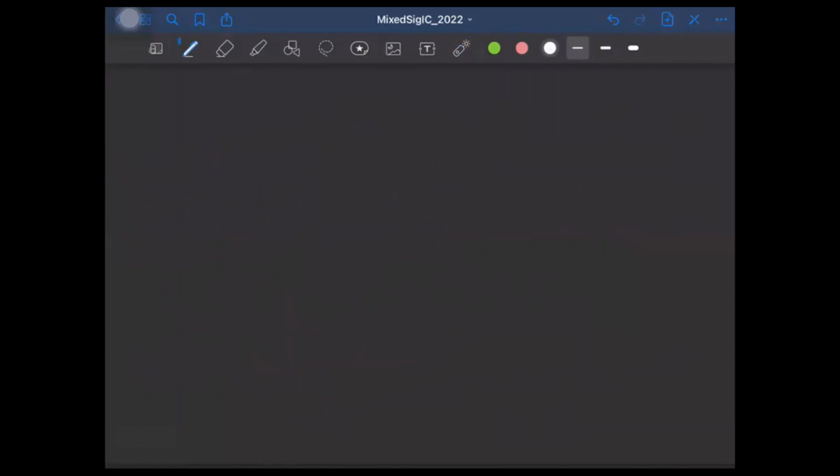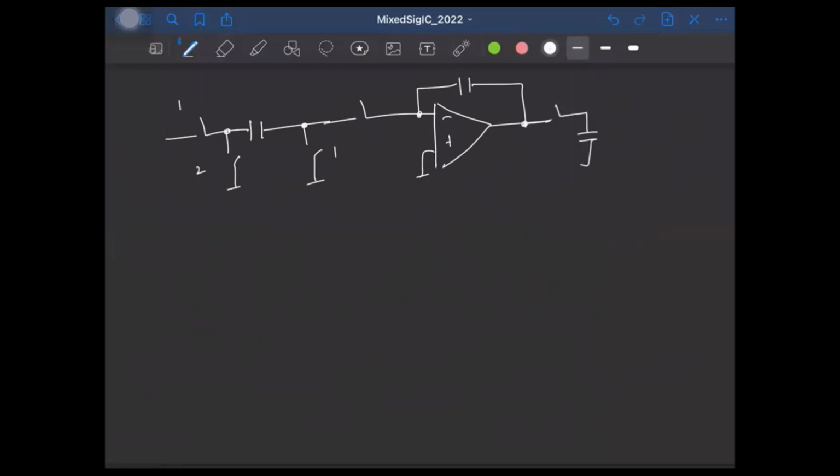And if you look at the switching circuit, we had the equivalent, we had the switching circuit like this. Right? So here again, we'll have parasitic capacitance associated with both the top and the bottom plate. So we have CP1 here, say, and let's say this is CP2. Okay. So now what will happen? Well, during the phase phi 1, we have the equivalent circuit like this. Right. So the parasitic capacitance associated with the bottom plate will not create an issue because it's completely discharged. While we still have the parasitic capacitance CP1 getting charged to the input voltage, right?